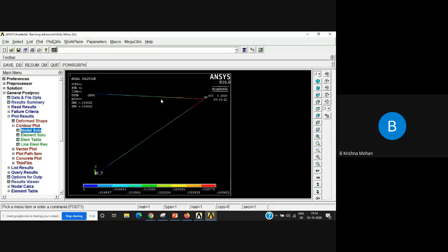And if you see, this is the deformation along the member. Since these two ends are fixed, the value should be 0 here. Blue color represents 0. Naturally, since they are fixed, you don't have deformation here. And deformation is maximum at this node 2, because a point load is applied. You can view the values here. You don't have negative values because it is a vector sum.